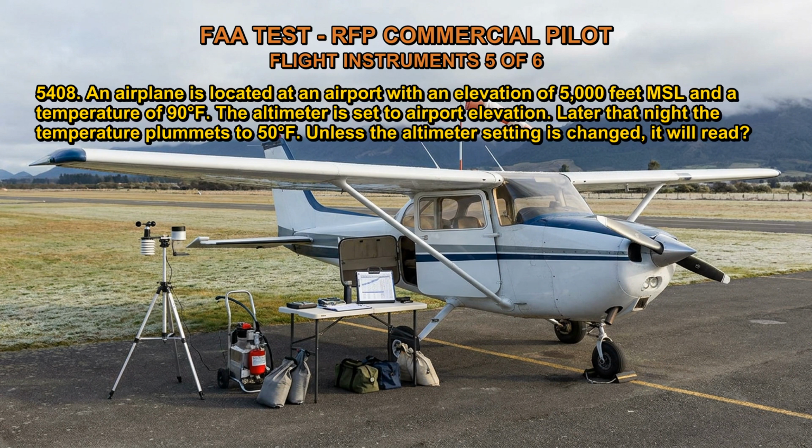5408. An airplane is located at an airport with an elevation of 5,000 feet MSL and a temperature of 90 degrees Fahrenheit. The altimeter is set to airport elevation. Later that night, the temperature plummets to 50 degrees Fahrenheit. Unless the altimeter setting is changed, it will read A. 4,800 feet, B. 5,000 feet, C. 5,200 feet.